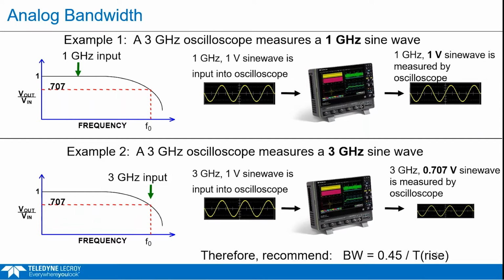And there's a little formula here that correlates it to rise times. And this scope here, I believe, is in the 175 picosecond rise time area as a 2 gig scope. So at any rate, that's the frequency I would be able to measure on signals.